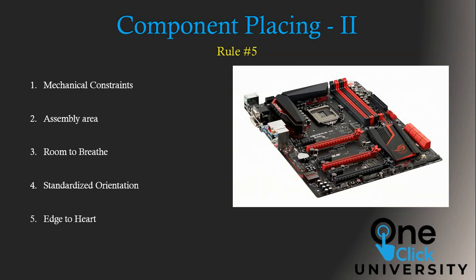Also, keep the parts on a single layer to avoid confusion while soldering and try not to overlap any parts. In rare cases, the smaller parts like the crystals may be placed below larger parts like microcontrollers. Otherwise, it is better to avoid overlapping.